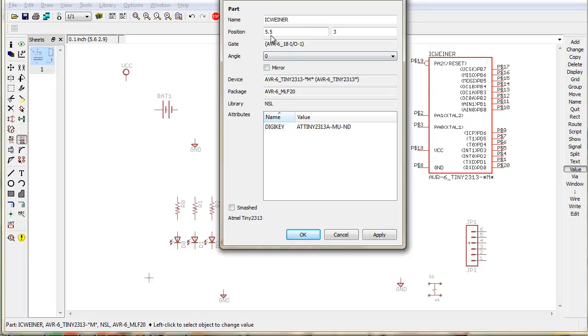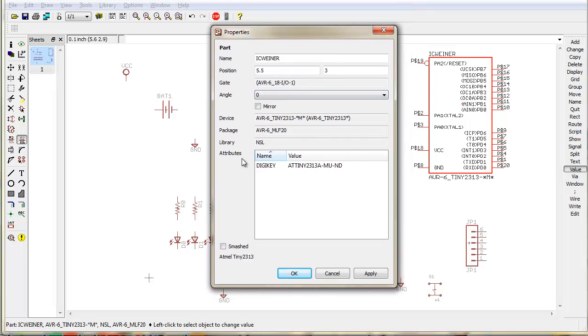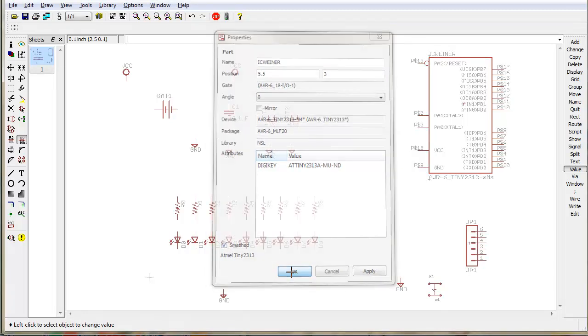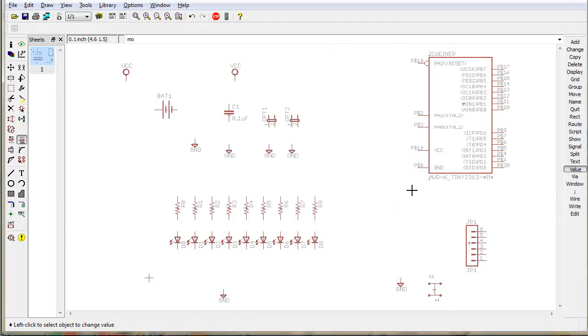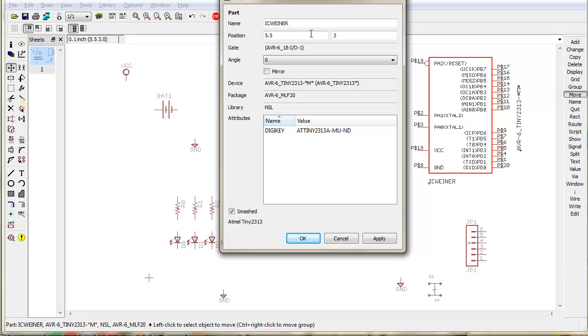and then there's smash. So we haven't looked at smash yet, so let's do it while we're in here. Smash basically allows us to move the labels. We'll select move now, and you'll see the crosshairs have appeared here on the two names. Now I can move and rotate those around and make them look all artistic and stuff, and that's what smash does. Move those around. Let's bring that back in. Change the name. Make something normal.